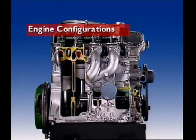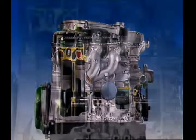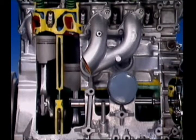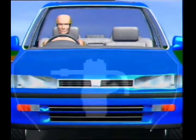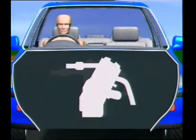The way engine cylinders are arranged is called the engine configuration. In-line engines have the cylinders in a line. This design creates a simple-to-cast engine block. In vehicle applications, the number of cylinders is normally from 2 up to 6. Usually the cylinders are vertical, but some manufacturers lean them to one side. Engines tilted in this way are called slant engines.